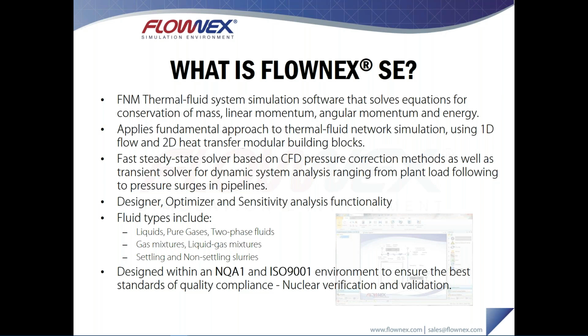The software itself is based around one-dimensional flow components and two-dimensional heat transfer components. This basically allows us to build a conjugate heat transfer network, simulating both the heat transfer and the fluid flow, and ultimately forming a full system solution. Flownex uses a CFD-based pressure correction method for both steady state and for transient or dynamic analysis. The software also includes a couple of analysis features just to help the engineers out.